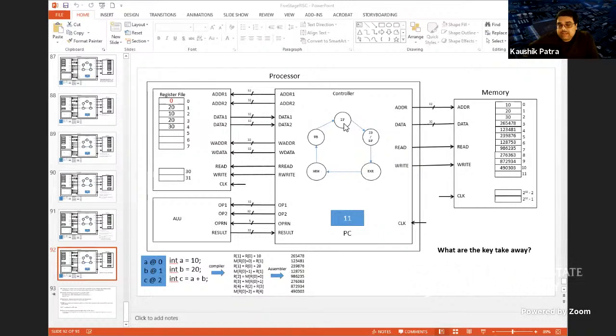Then the implementation becomes a bunch of if-then-else statements. If my state is instruction fetch, then set these signals. And if my state is ID/RF, then set the other signals to this. By the way, within that decision block, you may need to make some decisions based on the operation code. At this point, you will be parsing the incoming machine code and determining what that instruction really is. If it is an R-type instruction, or maybe a specific R-type shift instruction, then you need to take some specific action based on that.